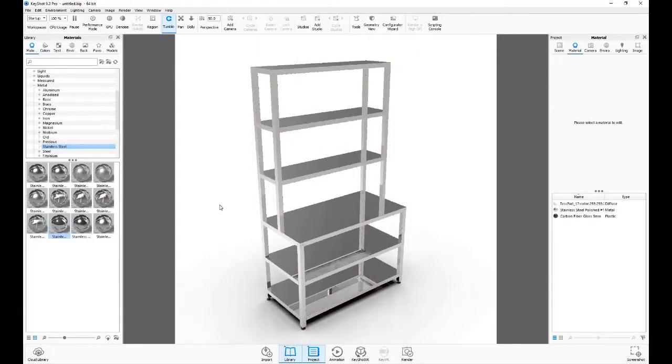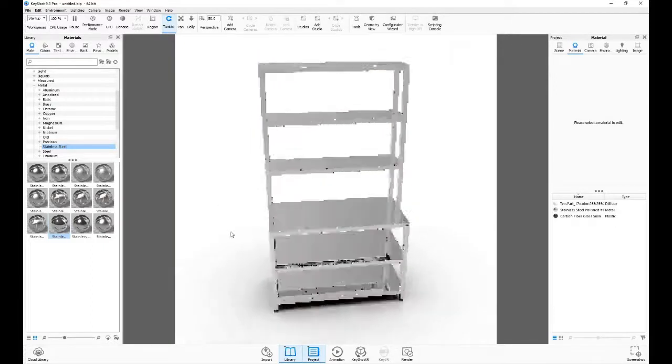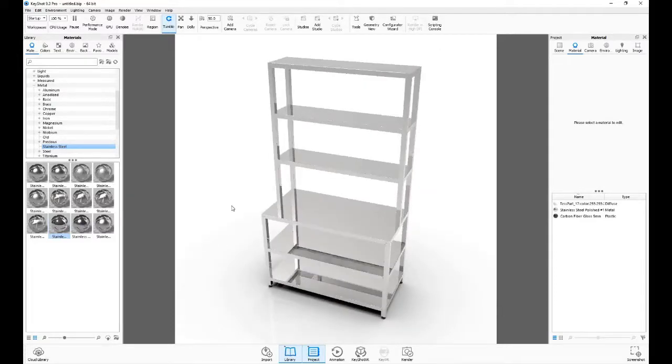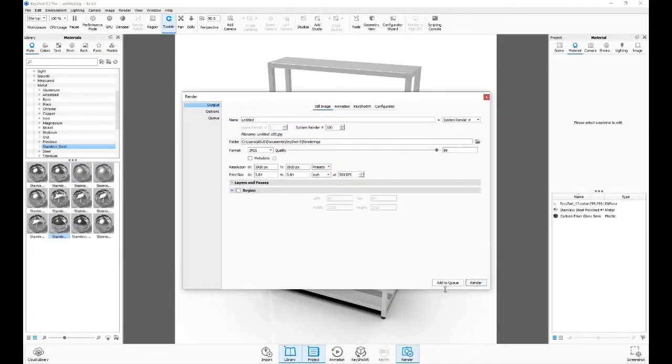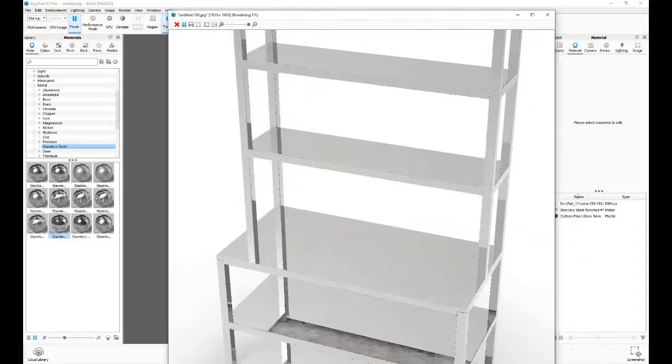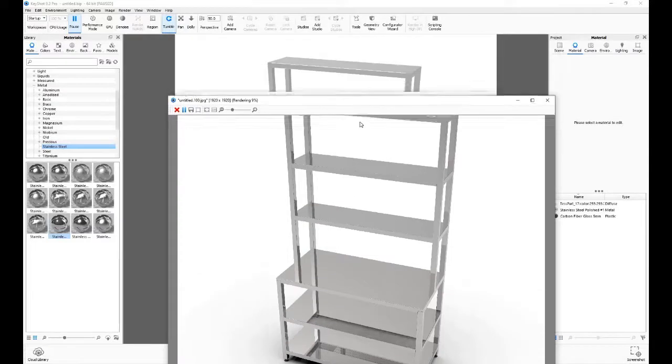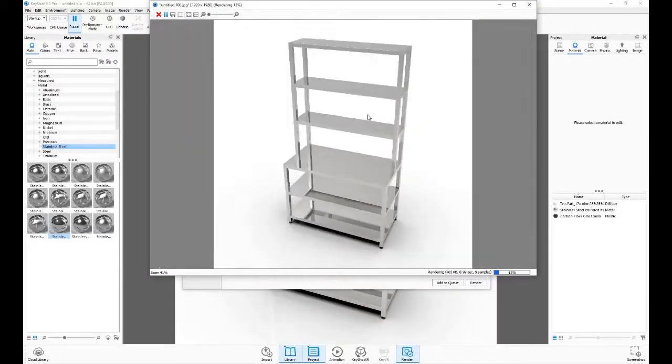We'll go ahead and add one more. This is going to be the opening width. This one I'm going to do as a numeric text box. Width can go from 1500 to 4000. And we'll go next. So you can think of these as the parameters that you're going to drive on your form. And then with these parameters, I'm going to create some rules that actually drive the dimensions and the features and stuff. So I'm going to go ahead and go into the rules.